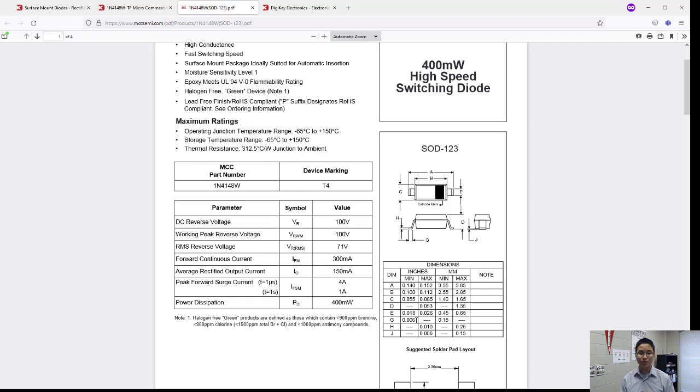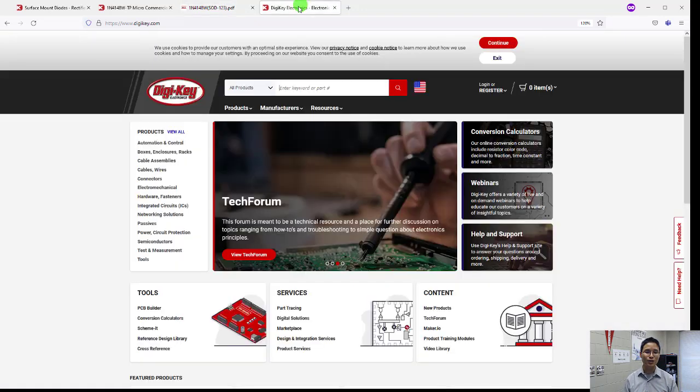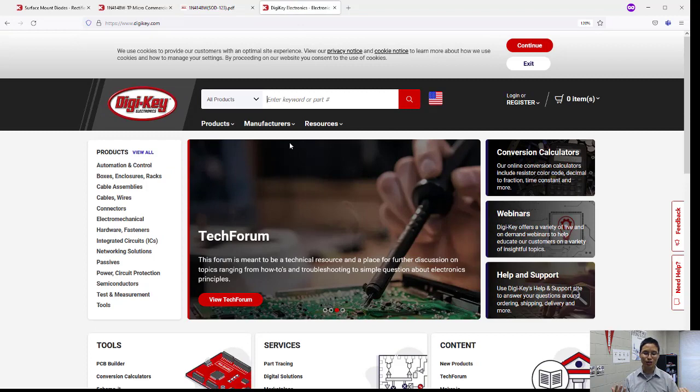Separately, remember to incorporate the mechanical design aspects with your PCB design and make sure that they interface and iterate. Have your mechanical considerations, such as how you're going to be mounting the PCB, incorporated into your PCB design process. And then finally, get familiar with and experiment with the larger electronic component websites such as Digi-Key in terms of doing your sourcing.